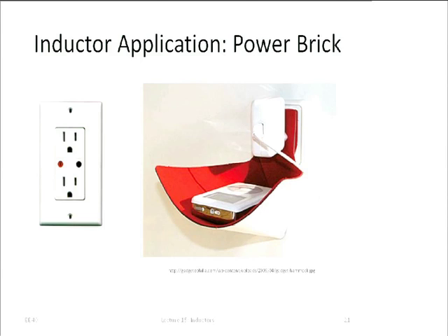And a voltage divider obviously can do this, but the problem with the voltage divider is that most of the power actually gets burned up, right? Most of the power that we get out of the supply just becomes heat, and it doesn't power our cell phone at all. And that, of course, is very bad. In that particular case, it just makes for a very, very hot charge.